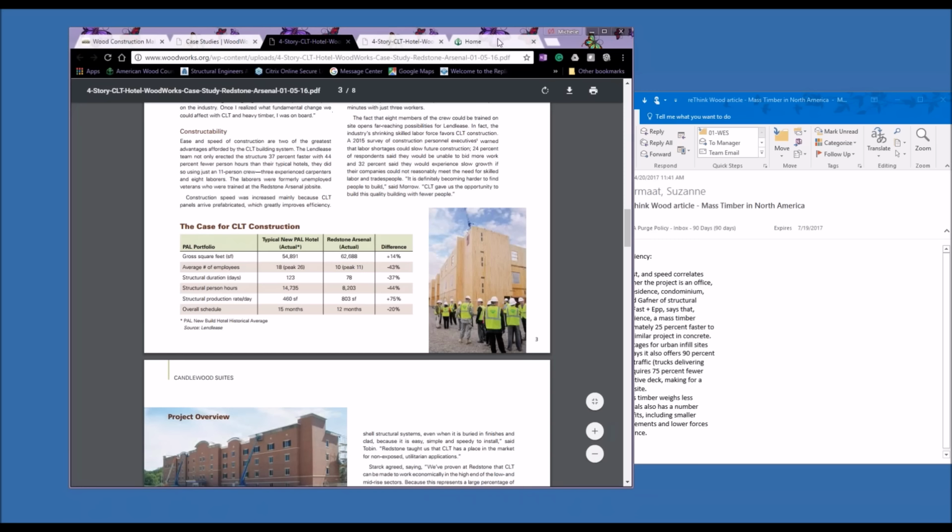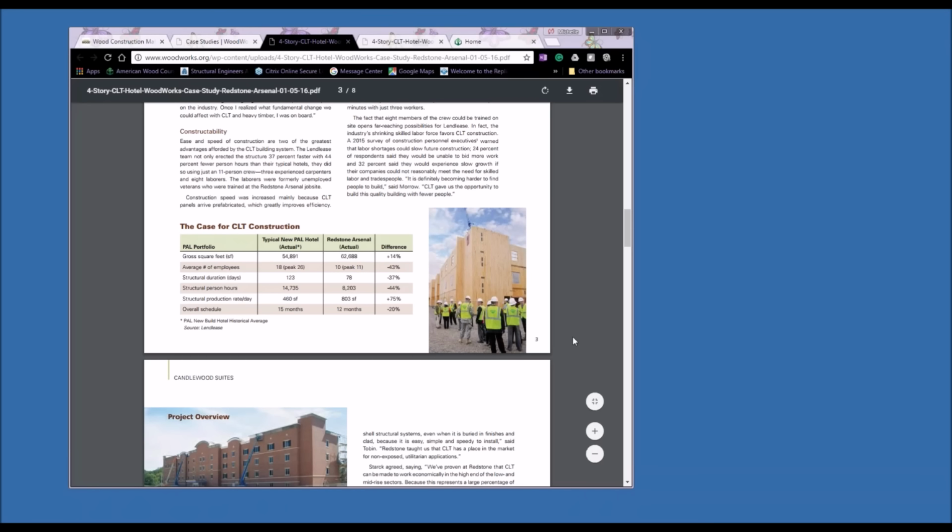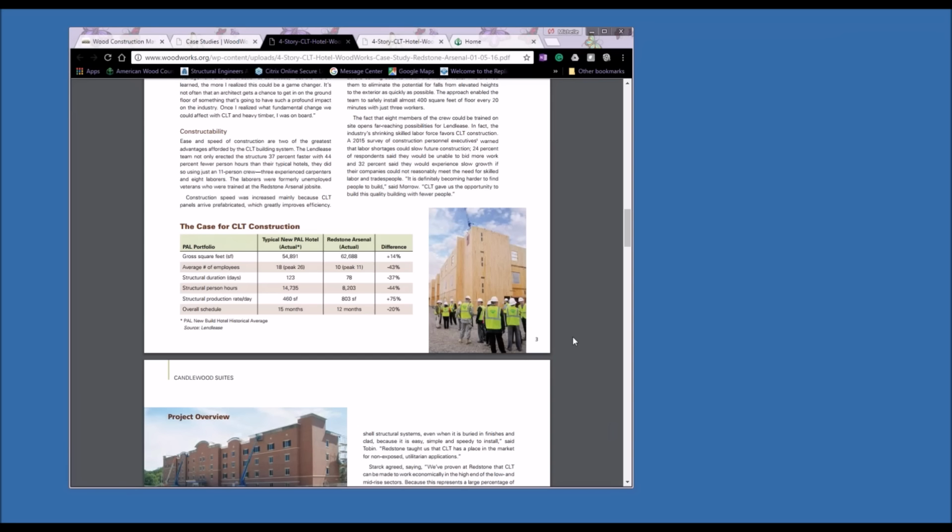Excellent. Yeah, thanks, Michelle. To add to that a little bit, it's definitely not just material to material, because I think some people are used to estimating for light frame, and they look at the light frame material costs and double that as their labor and material costs, and that ratio doesn't apply to a CLT system. But also, if you're comparing to a concrete or steel system, if you just compare the steel frame to the concrete or to the CLT frame, you're missing the cost benefit in lighter and smaller foundations under the CLT versus under the steel or concrete. So you really have to get beyond material versus material, because there are so many other benefits beyond just the material cost.